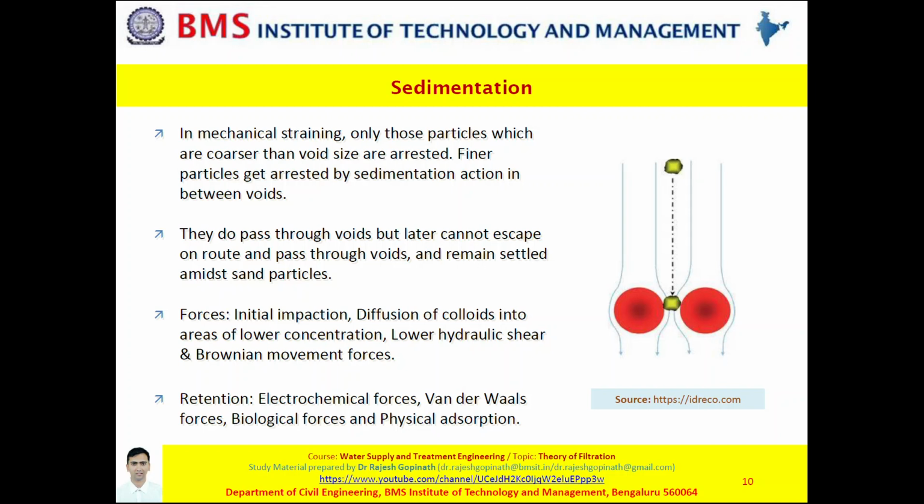Eventually, some of the particles may escape the grains of sand in the upper layer, but as they move downwards, they may get strained. So as the water constantly flows, these particles eventually get stuck in one layer or another. The particles stuck between the sand grains will not allow any other particles to pass through them. Eventually they behave like a sedimentation bed. So in filtration, multiple sedimentation beds are created, mini sedimentation tanks.